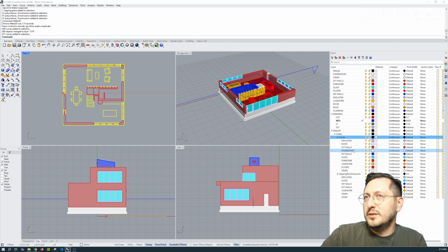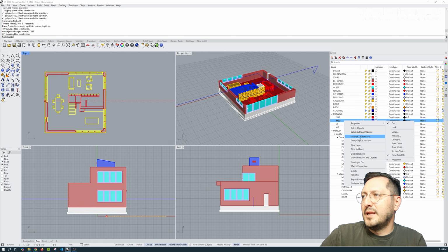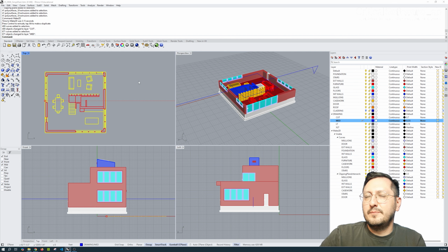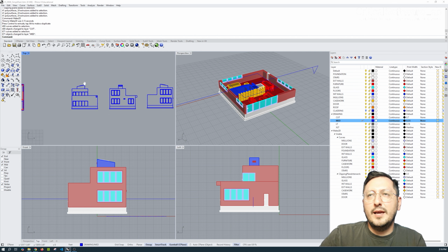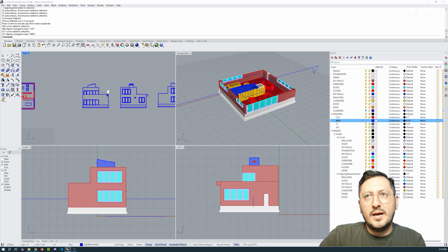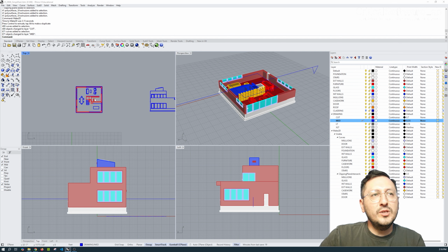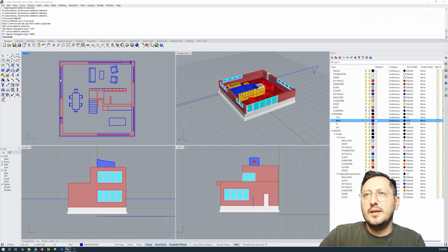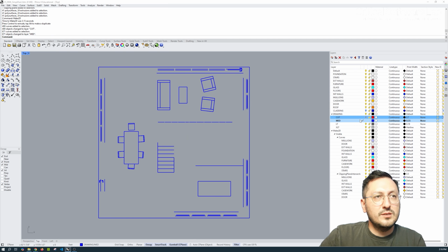I'm going to select all the sublayer objects, and I'm going to put those in the medium line weight layer. So now all of those have consistent line weights, and then we can go in and add extra lines. Like I said, we can treat these as regular 2D drawings, but Make 2D has done most of the work for us. And the important thing here is that it has allowed us to separate the cut lines from any lines that are beyond.